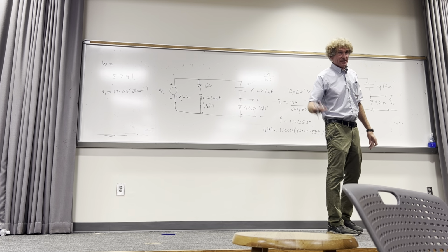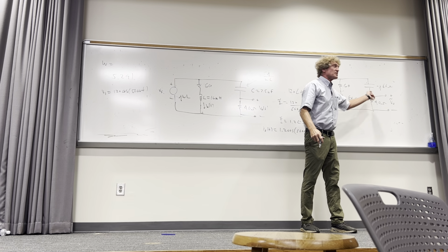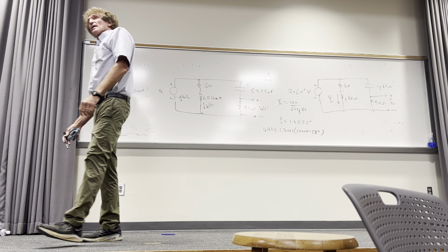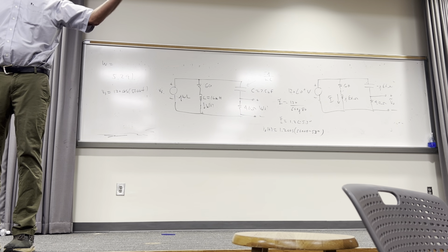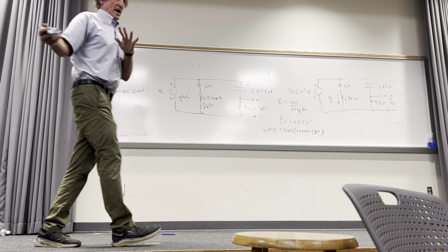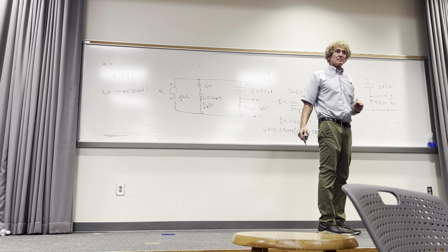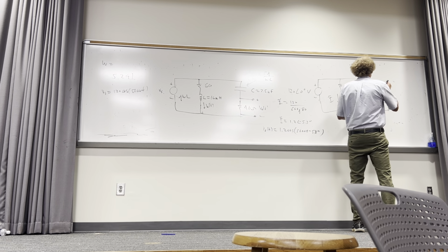Now how about this? I want this voltage in the phasor. How are you going to get it? You can do it so many different ways. Somebody said voltage division. Do you agree with that? You don't have to. You can get the current through there and multiply it by 40, but it's essentially the same thing, isn't it? So let's get this voltage in phasor form.